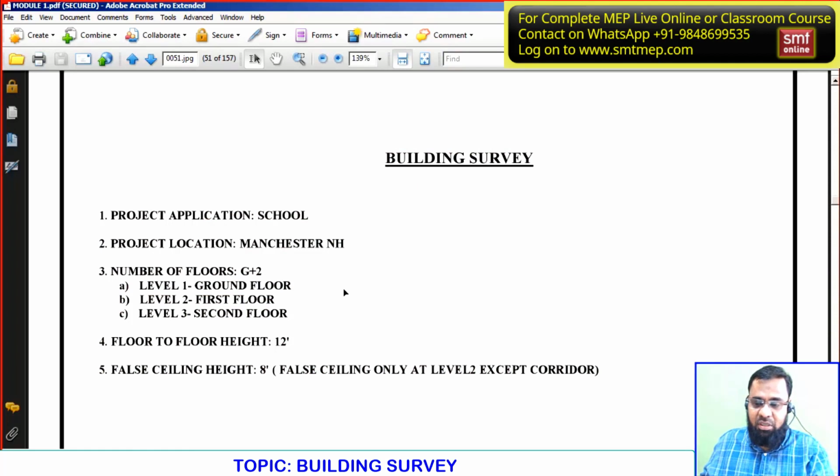For example, if you set the location related to any Gulf location, you will find more cooling load and less heating load. And if you set any location that belongs to a Western country, like the UK, US, Australia, or Canada, you will find more heating load and less cooling load. So you can compare this later after completing this project with this location.